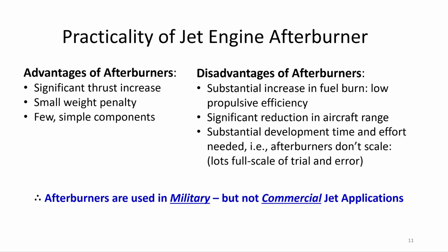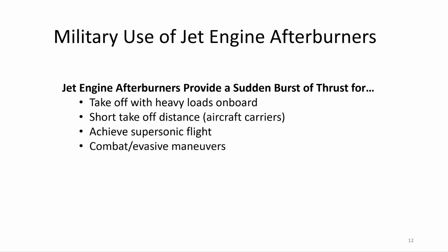So things have to be done trial and error and in full scale. So the bottom line is afterburners are used in the military but not for commercial applications because the TSFC, thrust specific fuel consumption, the equivalent of gas mileage in a car, is horrible for a jet engine using the afterburner. Now the military uses jet engine afterburners in a number of situations.